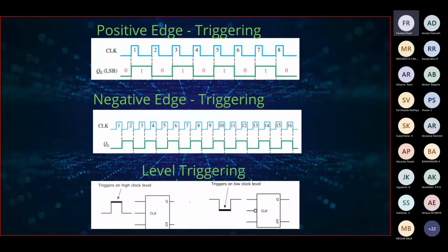If you look closely in the diagram, the data changes only during those times when the clock signal moves from a low state to a high state, and that's what the dotted lines represent in the first diagram. So only during those instances of time the data can change.